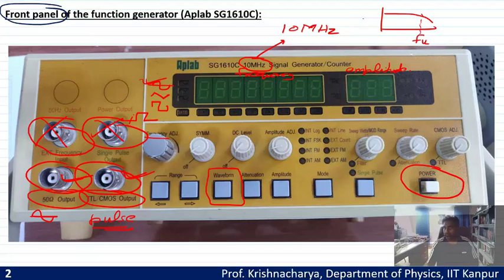That means its power output, or voltage output, will start decreasing. So you will not be able to trust the power drawn from this function generator. It can fairly be used for any signals equal to or below this upper cutoff frequency or bandwidth.